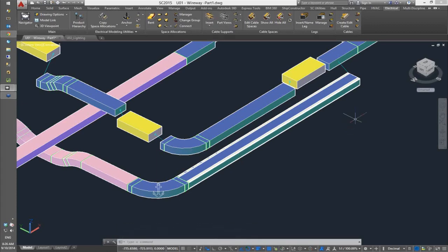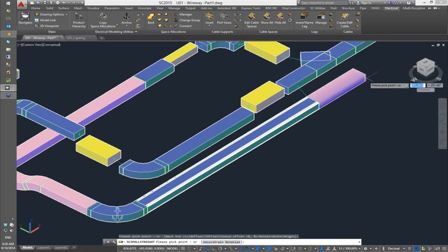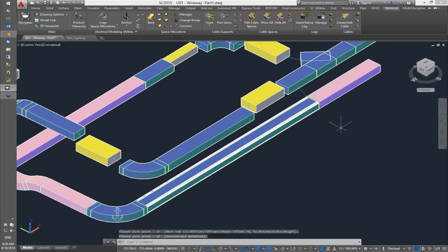So now we're going to put some hangers into this to support this tray. And just to extend the command a little bit or make it visible, when we insert by array, it works across multiple straight space allocations potentially, so one or more. So I'm just adding this one here because I'm supporting the tray, but I just want to show you the run going a little bit further on.